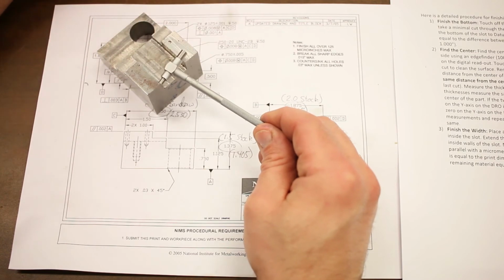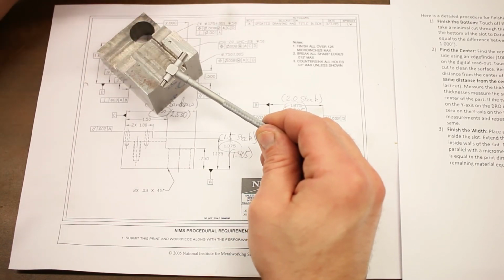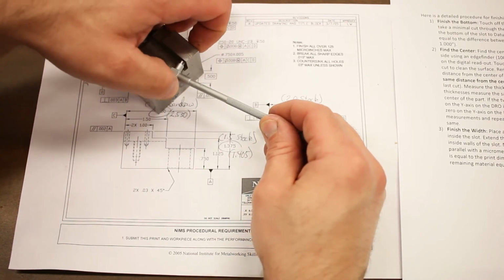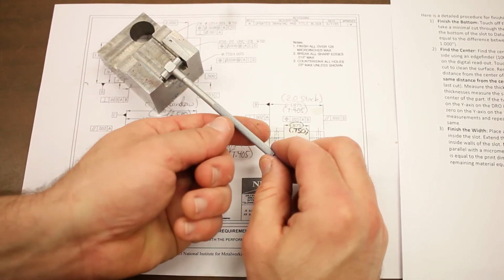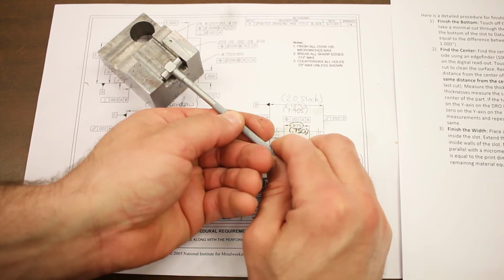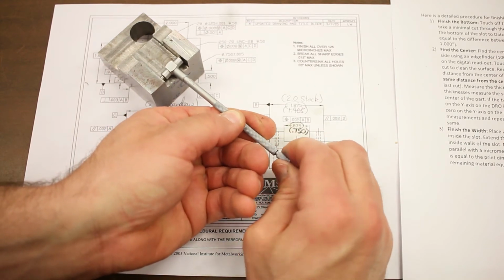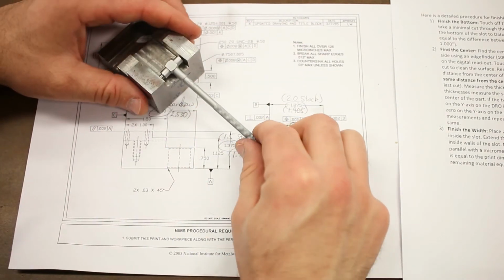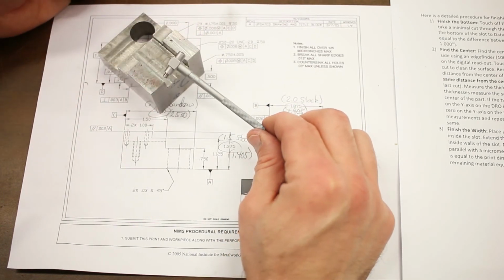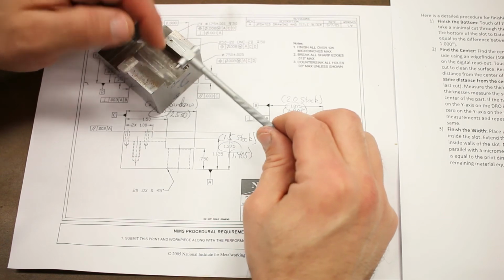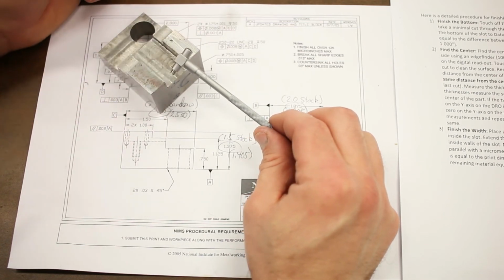So then some students put their thinking caps on and they think, well, why don't we use a telescoping gauge? Because that's what we use for the inside of holes, right? So why don't we just get that down in there, and then we just gotta find its proper orientation, like so, lock it down, and then very, very gently remove it and then measure over top of those contact points. This turns an innie into an outie and we can measure that with a micrometer.